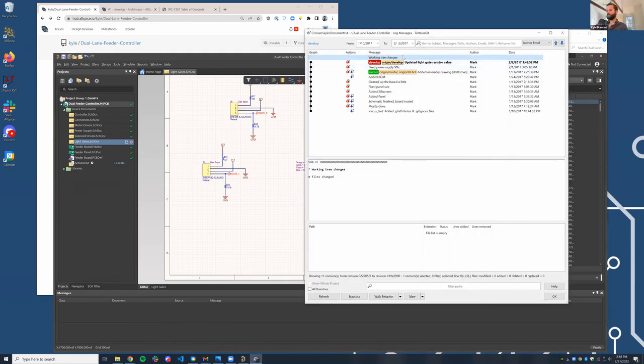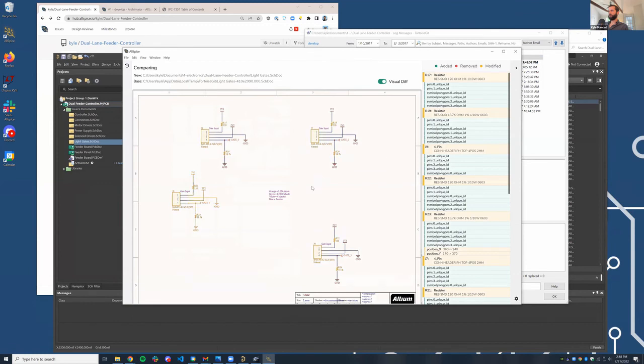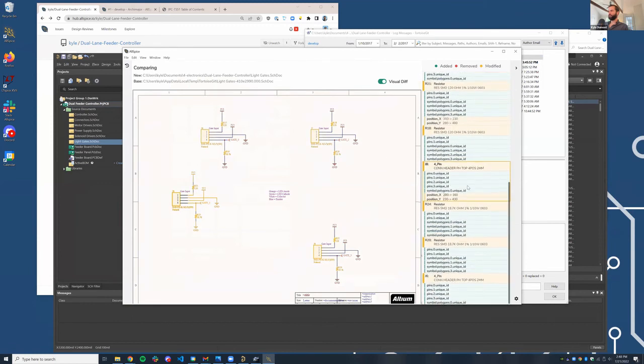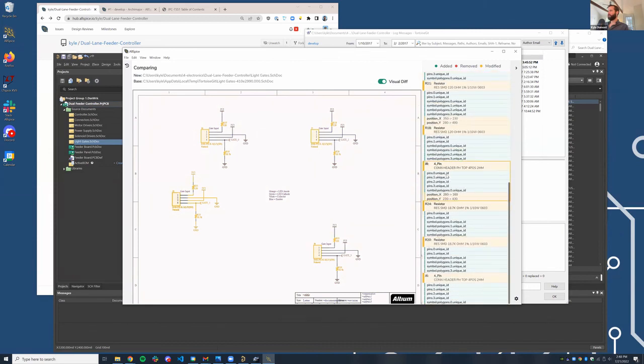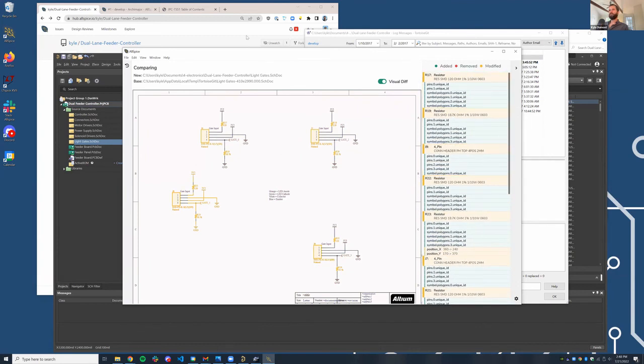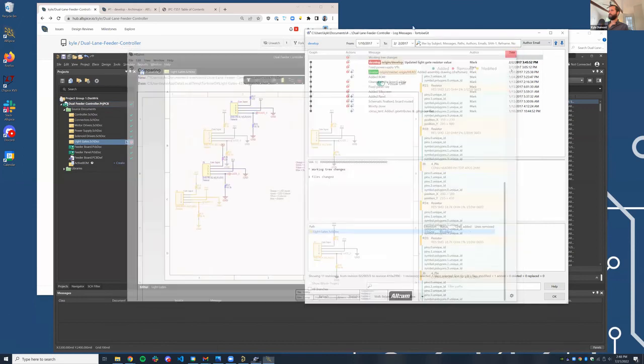There are essentially a couple ways to update this design. One is, you can see now, if I use Tortoise Git, I can see there's this design change, and there is also a local version of AllSpice that I can run for the diffs. Which also shows me that, because I'm using a new version of Altium, I've actually updated my unique IDs for these components, compared to what the old version was. So among other things, it can help you catch when Altium is changing things that you had not expected. But you can see also this position has been updated. Anyways, that's the local tool.